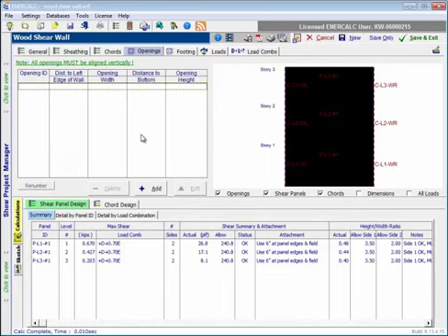The whole concept of openings is an interesting and challenging topic because it somewhat goes against the concept of individual full height shear panels, except that we were able to find a way to allow you to define openings within your shear wall panels. And then what we did was we basically just declared that the portion of the panel that's, we'll say, violated by an opening is completely without any ability to resist shear.